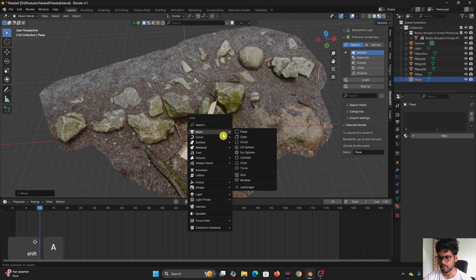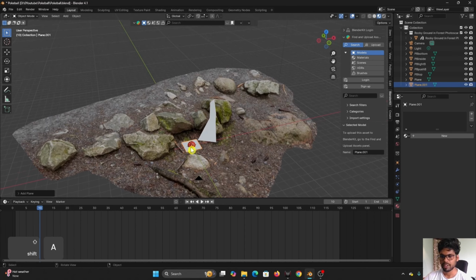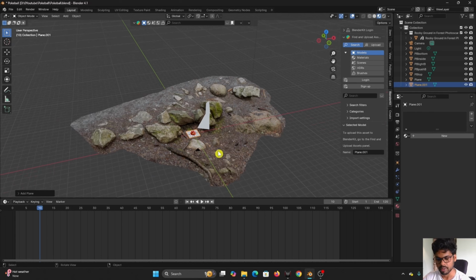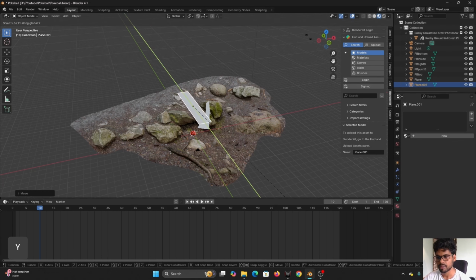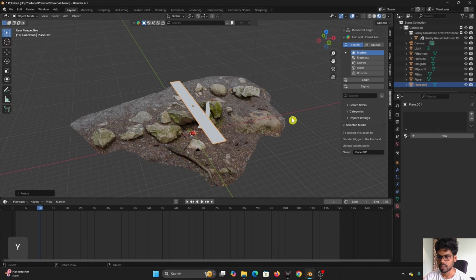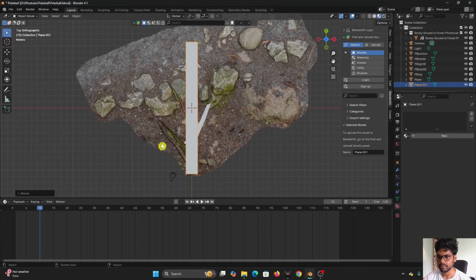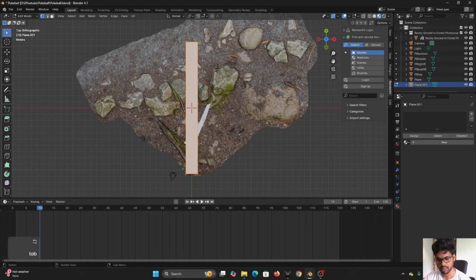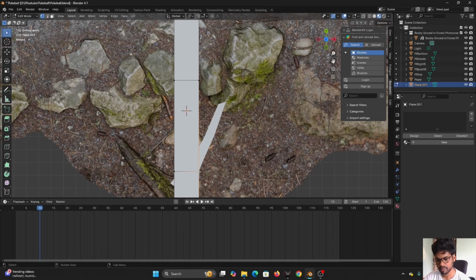I'm going to create a couple of planes. I think we can reuse just a single branch that we created. So let's move this first. Okay, and scale this along the y-axis. Something like that should work. Do you think we need to modify this, or let's just do it? Tab, Shift R. I think 2 will do. I want to place them somewhere here. Okay, select this. G.